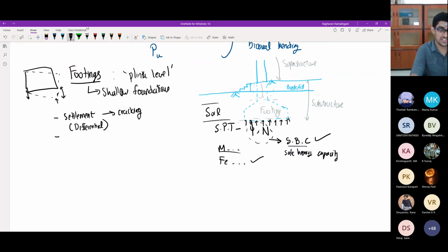So under this action of forces, one is up and one is down. What occurs in this plane because of this set of forces? So you have opposing displacements. One is going down, the other is tending to stay up because there is no settlement on one side. So what kind of force is set up in this plane? Torque. Torque, but it converts itself into a shear.